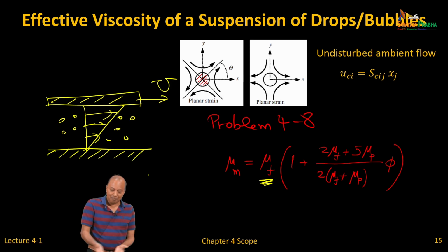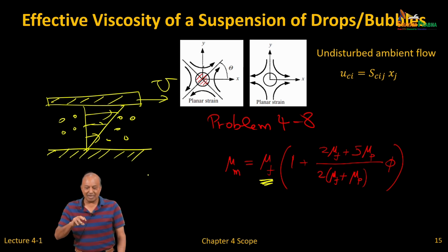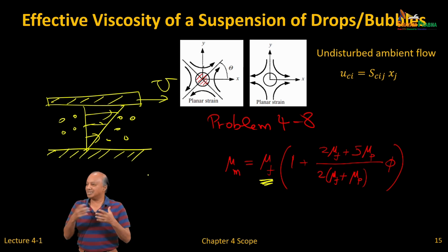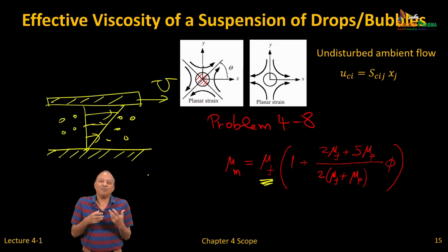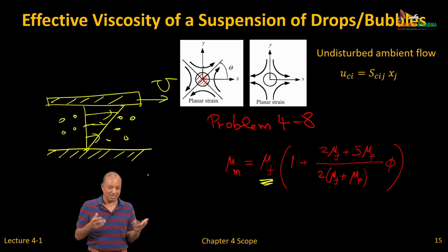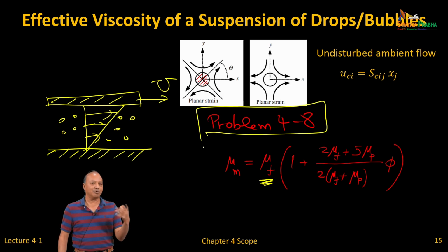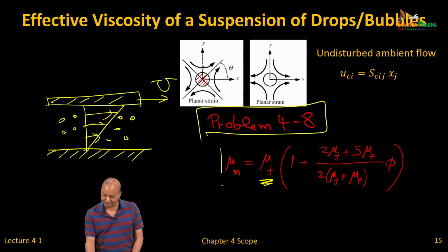So the same thing people have done for bubbles and droplets. Now a bubble or a droplet subjected to a strain field will also change the stress strain relation, but since the bubble can now move, in other words there can be fluid motion inside, how it changes is different, a little more complicated to solve, but you can solve this problem. In fact, in the book you can look at problem 4.8 where you can look at the details, but the net effect is what is very interesting.